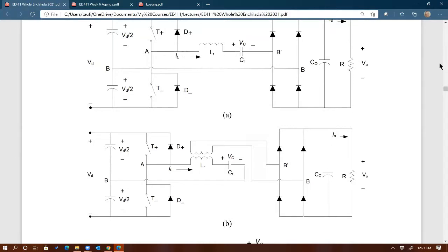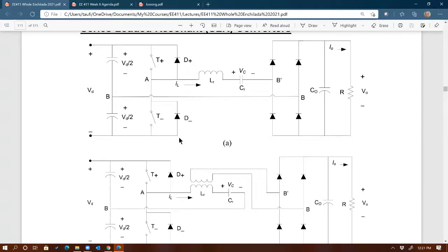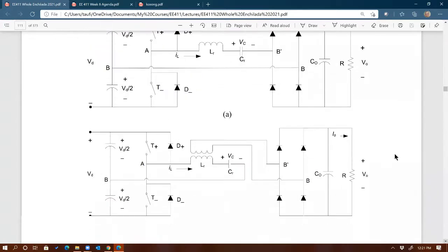It was used for an X-ray power supply, high voltage, from 3-phase AC to plus minus 120 kilovolts DC. So very high voltage, 40 kilowatts of output. And the topology that they used is exactly this topology right here, series loaded resonant.